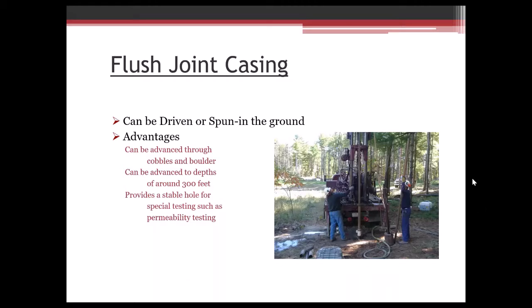You advance the casing, you clean out the casing with the trico and roller bit. When you're spinning the casing with the diamond shoe, and when you're using the trico and roller bit to clean out the inside of the casing, both methods use water.